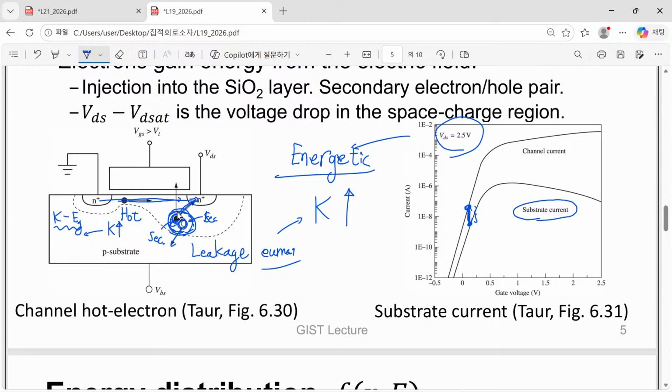But there is also another device which actually utilizes that effect. That is called flash. Have you ever heard about flash devices? In this case, they intentionally use this kind of mechanism. It means that once they apply a high enough voltage, they make many electrons hot enough, not just to 1.1, but a value of more than 2 eV or 2.5, even 3.